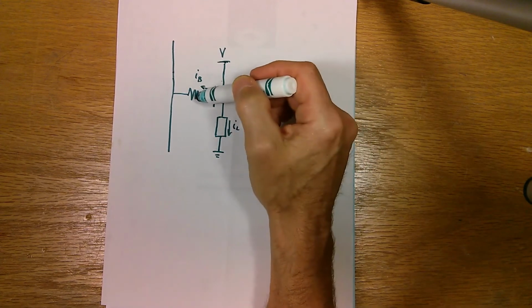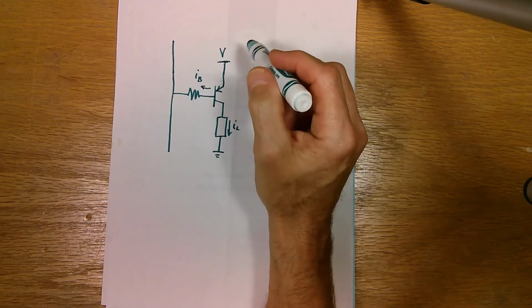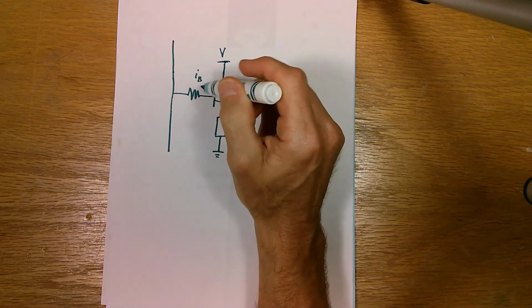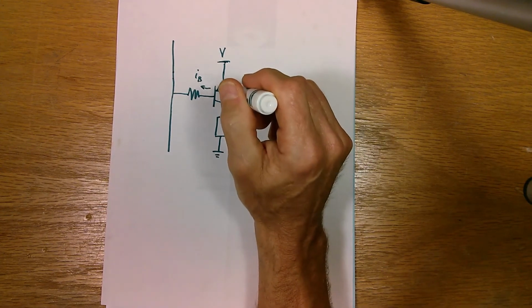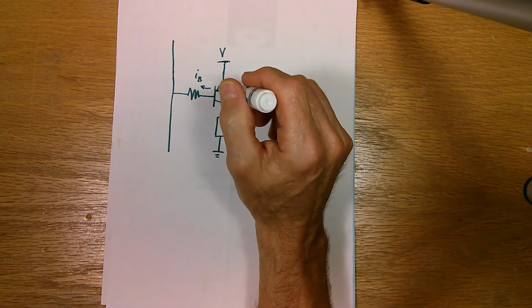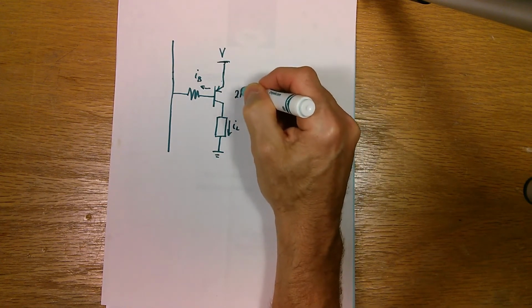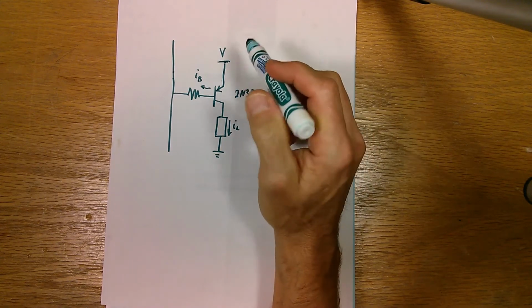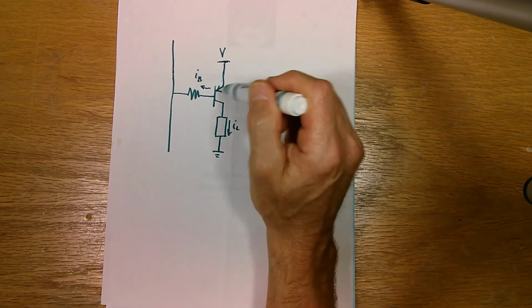Now, the calculations for the base resistor are the same as the previous one. The collector current flows this way through the load, the base current flows this way. This transistor has an HFE as well. When you look through the data sheets for a 2N3906, which is what this one here is, you may find that the HFE for a PNP transistor is lower.